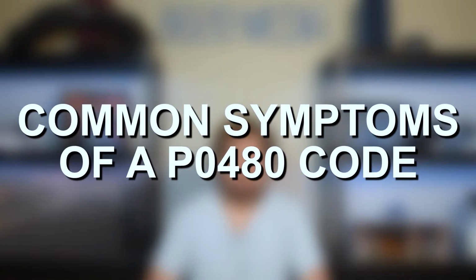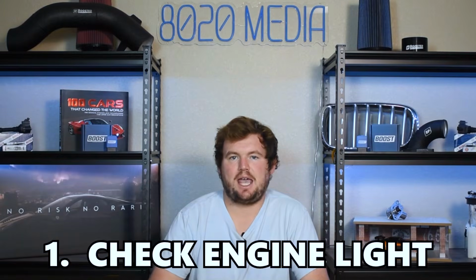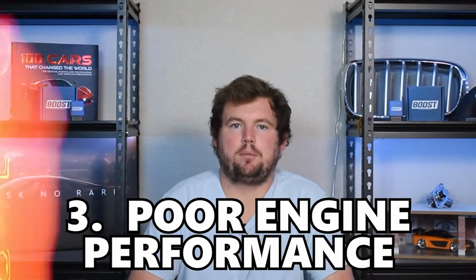So a few of the most common symptoms associated with this fault code include the check engine light turning on, the engine overheating, and potentially poor performance. Now, poor performance would most commonly occur when the engine is actually overheating, and in turn reducing performance to prevent any additional engine damage.